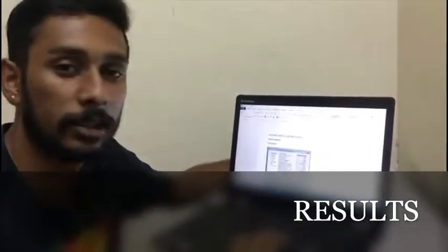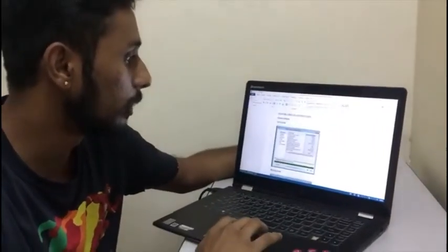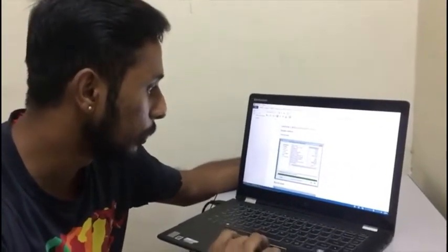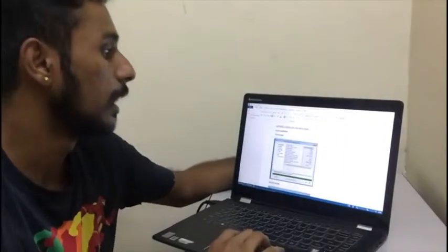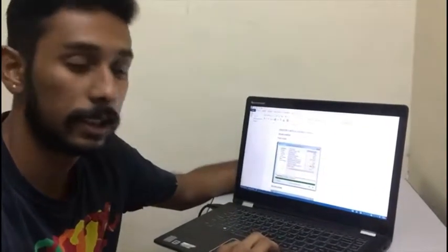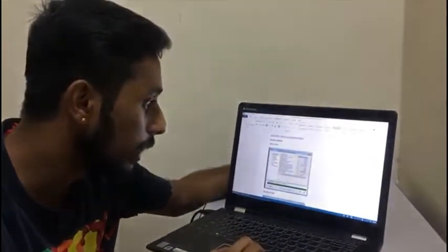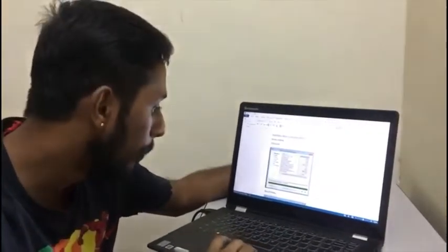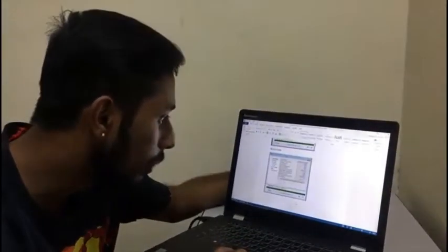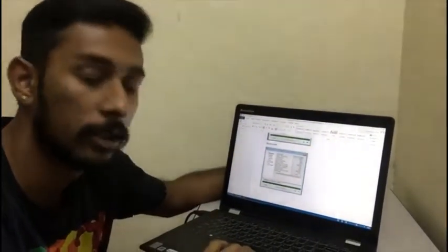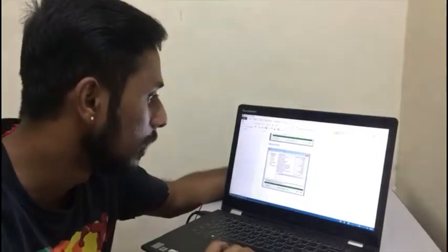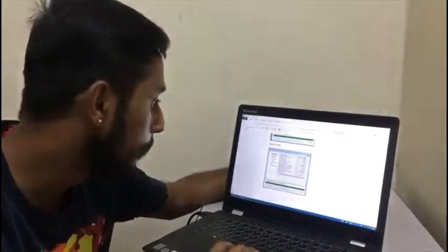My name is Sudarshan. Today I'll be talking about results. Starting from the stream conditions, the feed stream. The properties of the feed stream, as you can see: the temperature is set at 16 degrees Celsius, the pressure is at 0.2 bar, and the flow is at 935 kg per hour. Going down, the recycle stream has a temperature of 125.3 degrees Celsius, a pressure of 1 bar, a flow of 118.5 kg per hour.